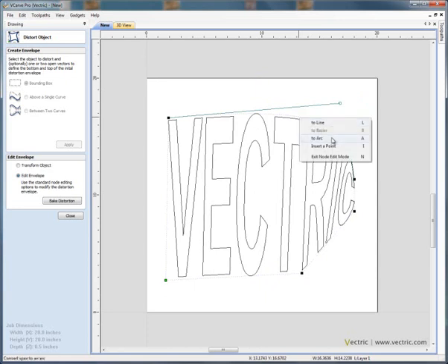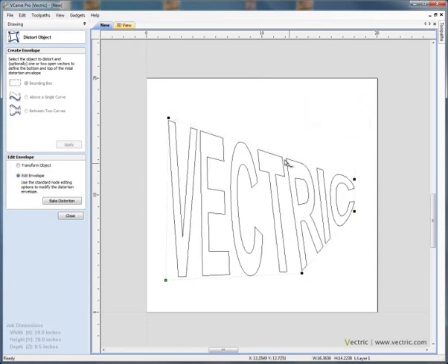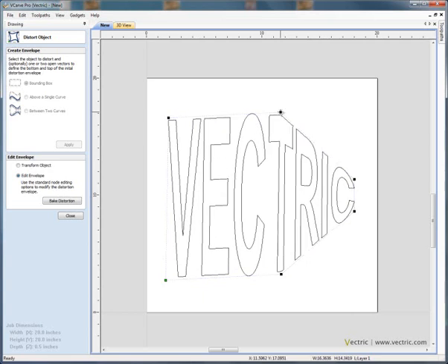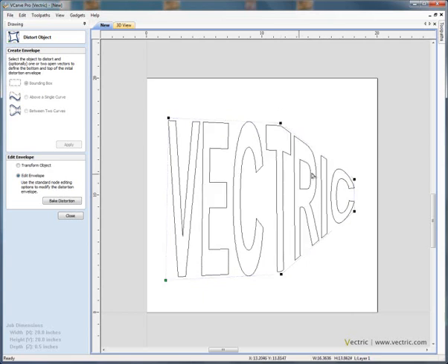We could convert this back to a line and insert a point. So insert a point, or press the letter I, and just click and drag to change the perspective and change the way that the text appears in the 2D view. So it's great for artistic designs, great for sign making, very quick and easy to use, and you can get some very interesting results. When you've finished editing a particular project, we can bake the distorted object.